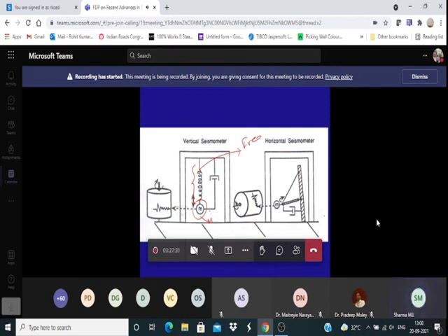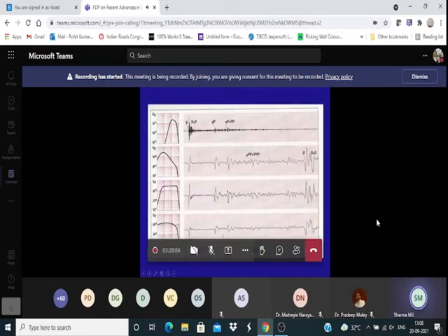And you know that depending on the ground motion natural period and the natural period of this, you will have the resonance curve and you will be recording faithfully some of the motion. So it means that the whole ground motion cannot be recorded by a single seismograph, but it has to be recorded by a combination of these two. Let me give you one example. This is one of the earthquakes. This is a single earthquake, and on this, what we have done is that on one platform we have placed 4 seismometers.